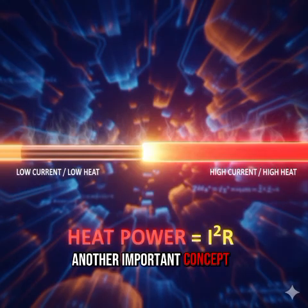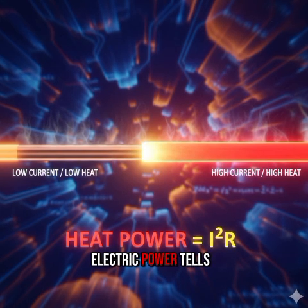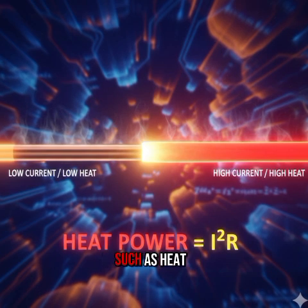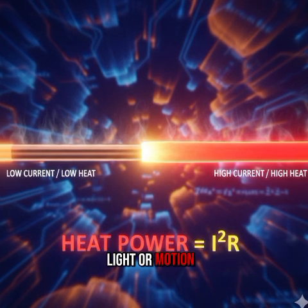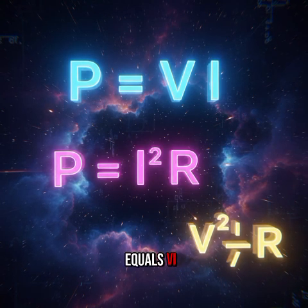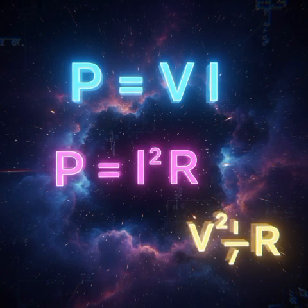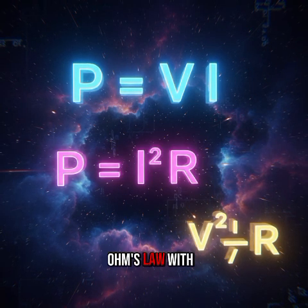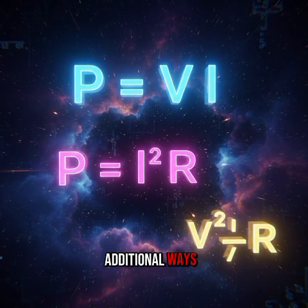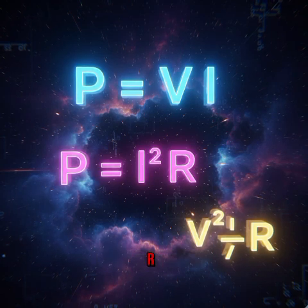Another important concept connected to Ohm's law is electric power. Electric power tells us how fast electrical energy is being converted into other forms such as heat, light, or motion. Power is measured in watts and is given by the formula P equals VI, meaning power equals voltage multiplied by current. When we combine Ohm's law with this power formula, we can express power in two additional ways: P equals I squared R and P equals V squared divided by R.